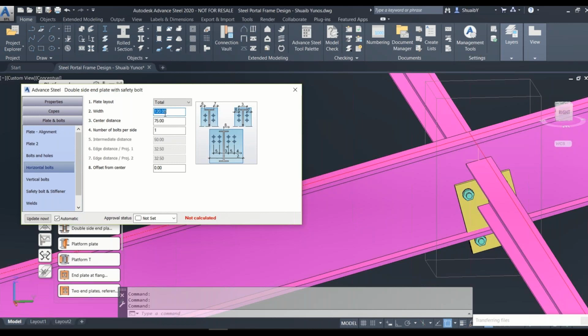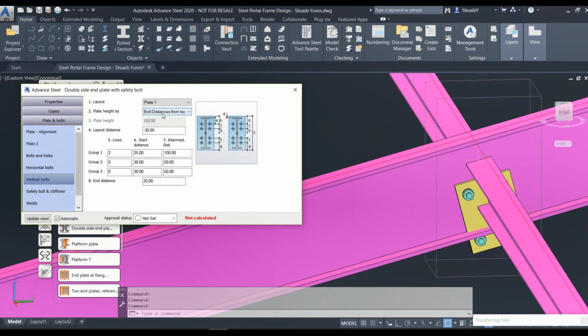Okay, so let's go and do this again. You can see the same offset of -30 is there. Let's use it from the top. Let's change that to 20 because we know the previous plate, how we liked it. And of course, you're going to do a plate height of, let's say, 150.